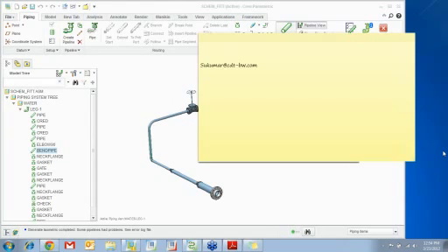Now, it also depends on whether you are creating the wires in a schematic. If you create them in the schematic, you can create all the wires and group them together in the schematic, if that's what you're asking. Yes, you have to create them individually and then group them. And then you can come back into Creo and route them all at once as a group. You don't have to route them individually. Hope I answered the question.